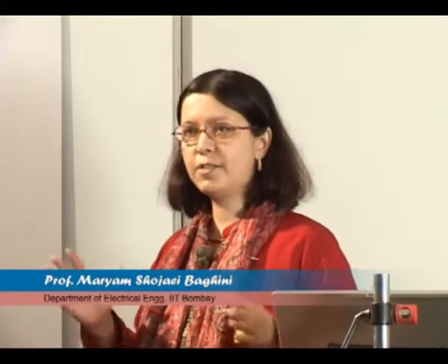Because if you have a bias point in the current of I and now your current becomes 2I, either your transistor in some part of the circuit may be driven into ohmic region or vice versa, some parts of the circuit may go into off region. So that's why it's very important. And in analog design, always we deal with all these variations. So it is not easy to escape from them. So let us see how we can omit them one by one.